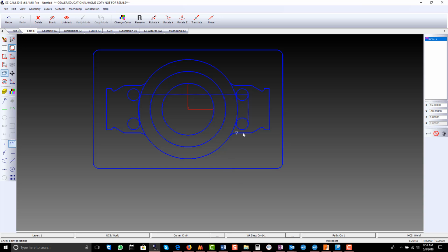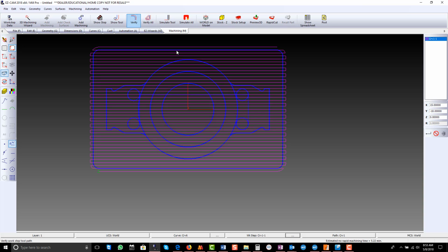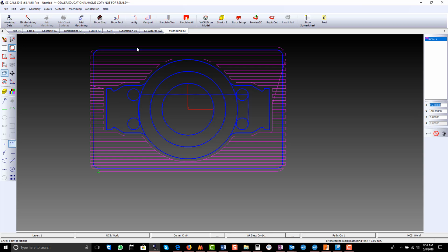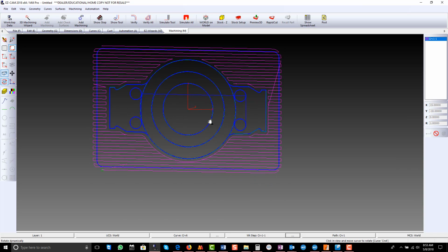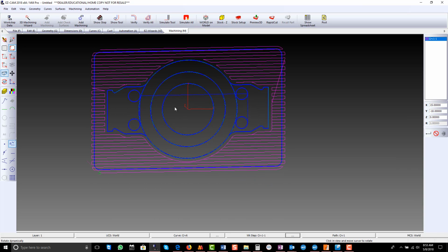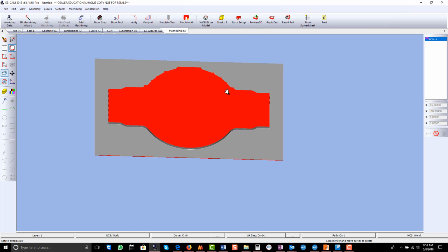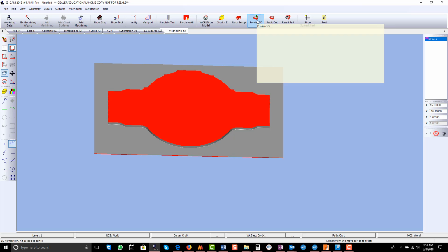Then we want to add the inside, the part boundary. So if I looked at it right now, it machines the whole top of the part, because all we had was I double clicked on the stock. So we're going to include the part boundary. So we just go to add machining curves, verify. Look at a 3D preview. And we can slow that simulation down.